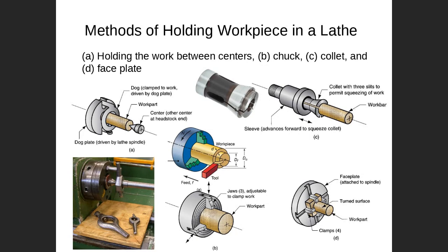So here you can say, this is the tailstock. This is the tailstock here. You bring the tailstock to here. When you bring the tailstock to here, in the middle, in the center, this will ensure the center will be in the middle, and then you clamp individually. Then you can clamp non-circular or non-homogeneous shapes. So we call it a faceplate, right? Is it clear?